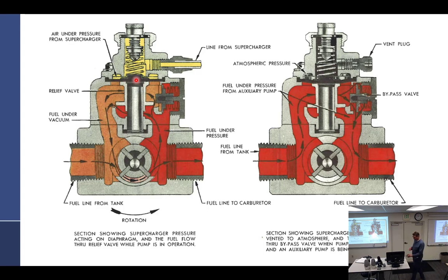And I'll say something like, why? Yeah, it's left-hand thread. You're like, yeah, so what? During the eventual oral, we could just say it doesn't matter, other than the fact that you just know that it increases pressure if you turn to the right. See how it's backwards? When you screw it to the right, the nut's going to drop down, putting more pressure on the spring, which is going to increase pressure.